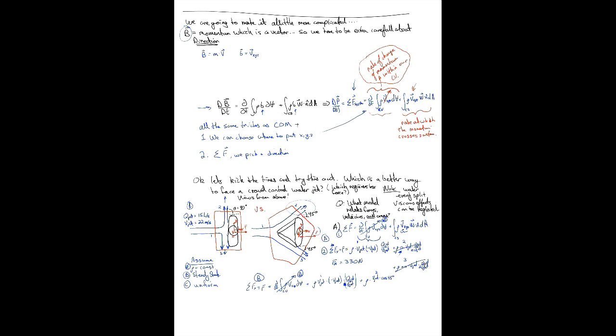And now we have to multiply that by the velocity of the fluid relative to our control volume surface, which is just v jet. It's leaving, so it's a positive dot product. And we multiply by the area, which is q jet over v jet divided by 2.